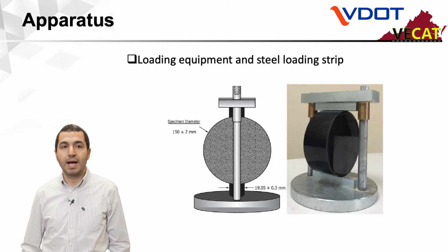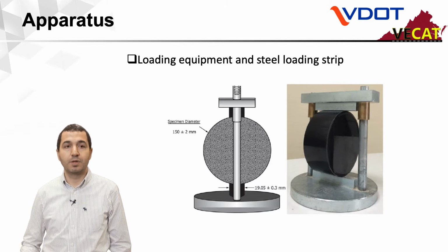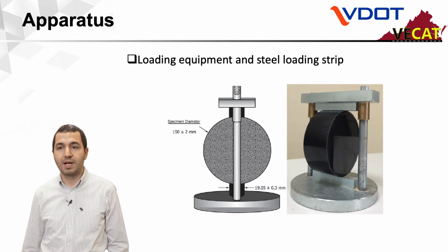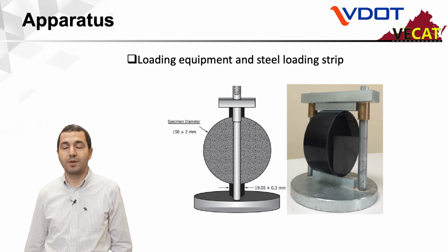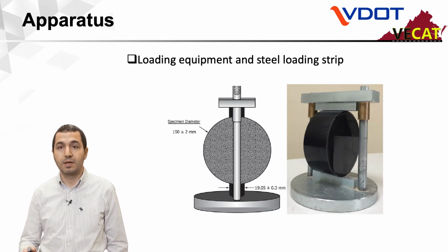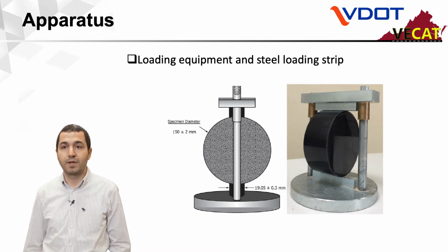One thing that I want to add that is of importance here, standard refers to two different dimensions, 4-inch and 6-inch diameter specimens. But when using 6-inch, please make sure that you are using the right loading strip as shown in this figure here.